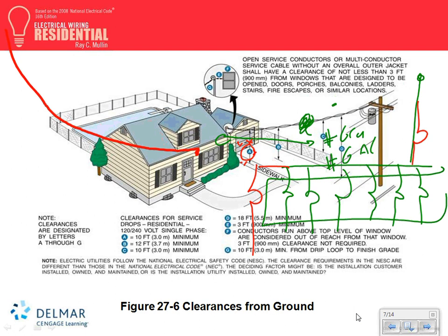These are the most important 2 numbers you're going to remember. If you're doing residential, minimum service to residential is what? 100 amp. If I have non-residential, other than residential, your minimum service to a pump on the side of the street, it's going to be a 60 amp service, regardless of the voltage.